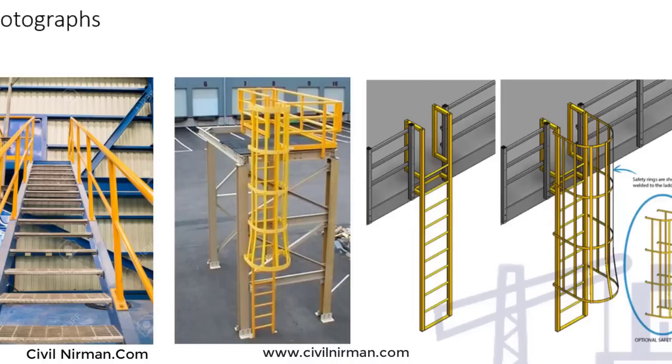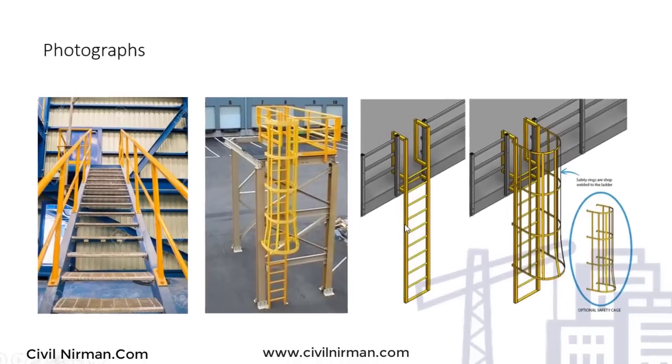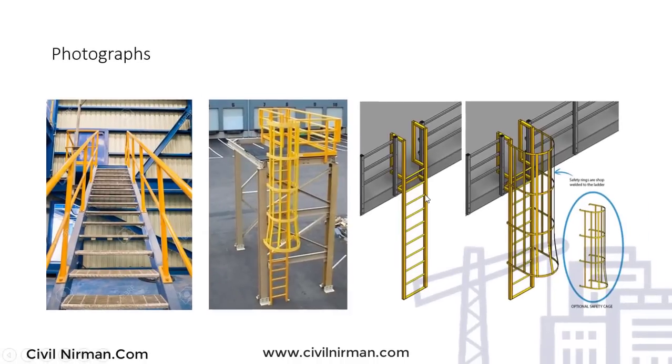So when the ladder length is more than 3 meters, generally we go with a caged ladder so that additional protection will be available. While when the platform height is not more than 3 meters, then we can generally go with a normal ladder without having any cage.